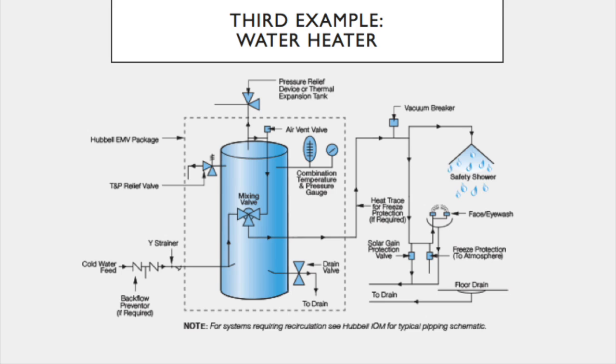The third example of a unit operation is a water heater to heat the water throughout the UConn campus. The total process is to heat up water to use for various needs. The unit operation involved is the heat exchange process. The supply pipe of the heater routes cold water to the bottom of the tank through the dip tube. The hot water delivery pipe takes water from the top. All water heaters have a valve that will open if either the temperature or pressure of the water exceeds a safe limit for safety precautions.